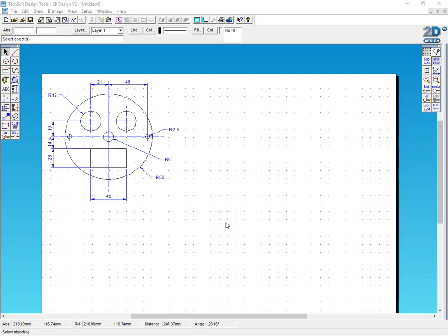Alright, things are getting a little bit harder now. Let's move on to the face. Let's think of a strategy for this face. I think first of all we'll draw this outer circle with a radius of 52 millimeters. We'll then use the attach tool to find the centre and draw these centre lines that go down the centre.